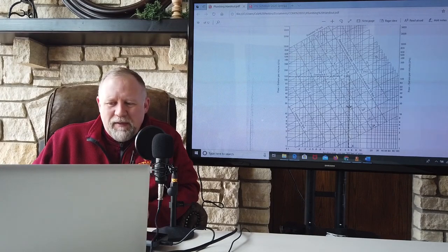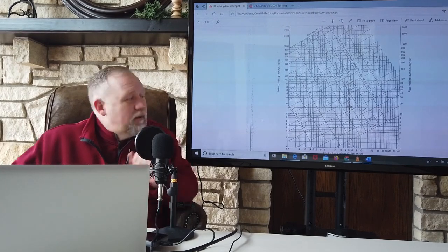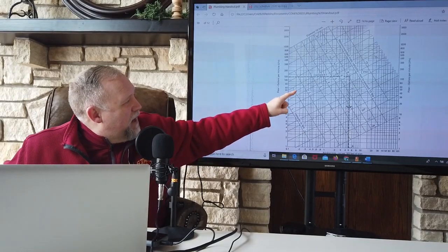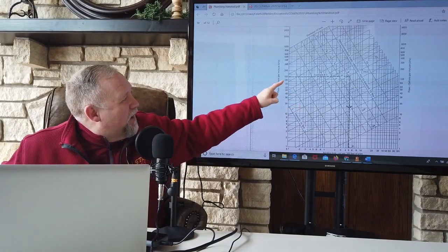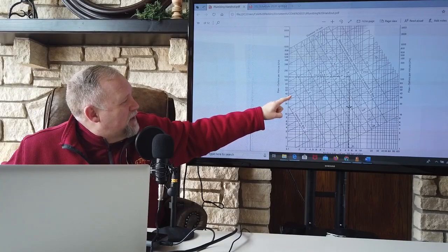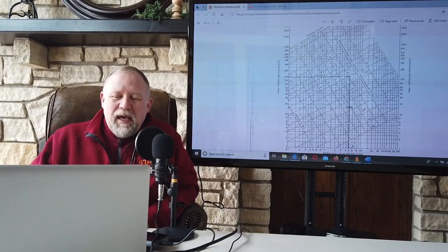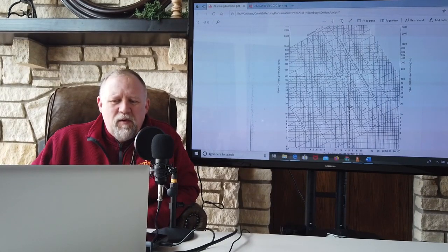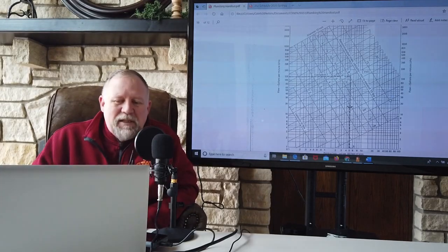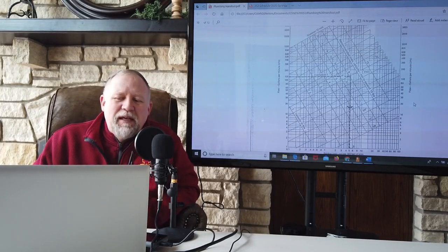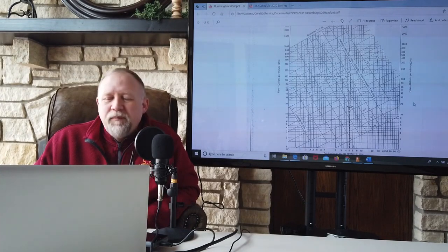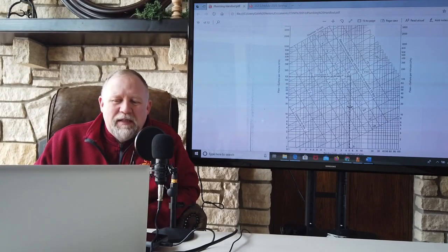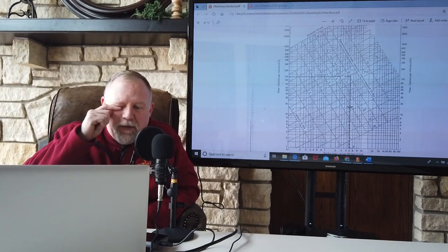Now, a couple of caveats about this Moody chart. See that they've got pipe sizes that are like 5-inch pipe size and 3-inch pipe size and 3.5. Yes, those all exist, but they are very unusual. They are not standard pipe sizes that you would normally go purchase and install. However, since this is an academic exercise for a test coming soon to you, the right pipe size is the smallest one that still falls under that velocity limitation.